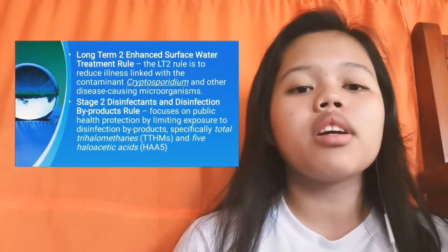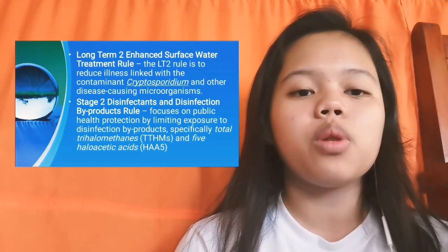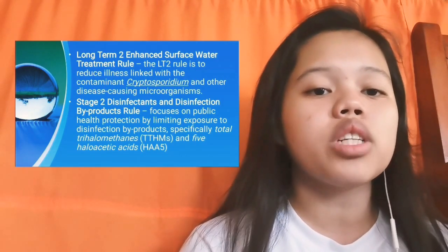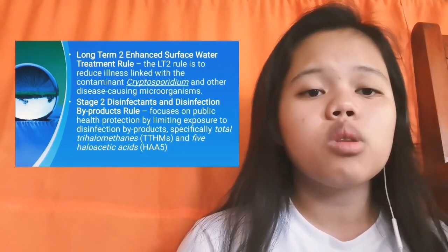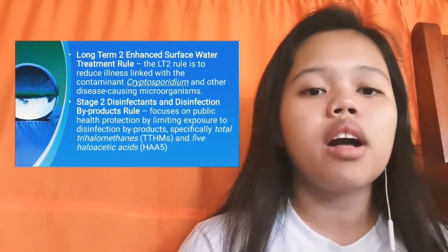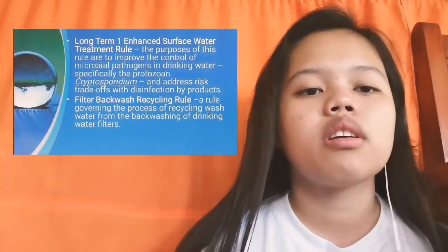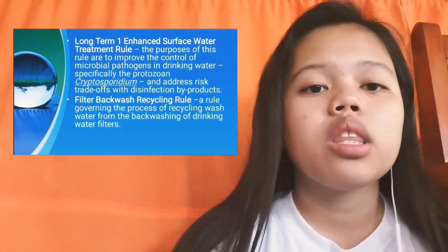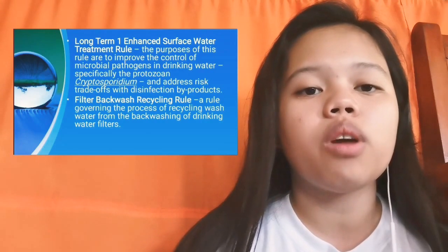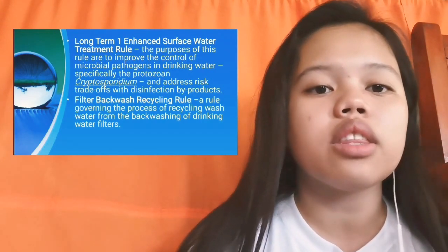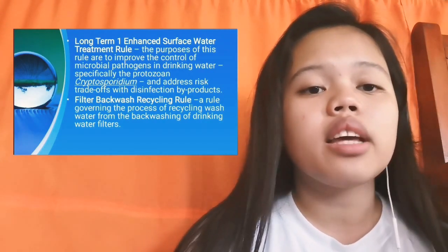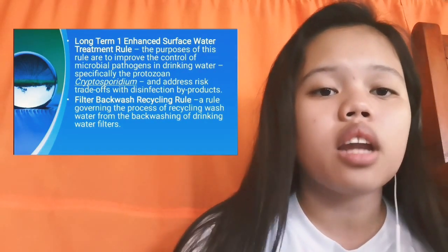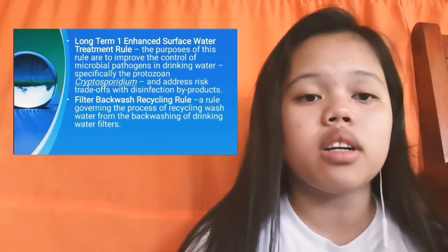Stage 2 Disinfectants and Disinfection Byproducts Rule focuses on public health protection by limiting exposure to disinfection byproducts, specifically total trihalomethanes and five haloacetic acids. Long-Term 1 Enhanced Surface Water Treatment Rule. The purpose of this rule is to improve the control of microbial pathogens in drinking water, specifically the protozoan Cryptosporidium, and address risk trade-offs with disinfection byproducts.